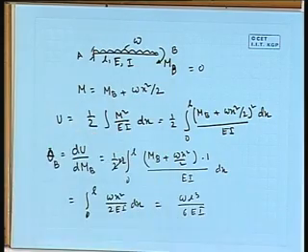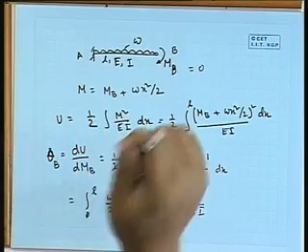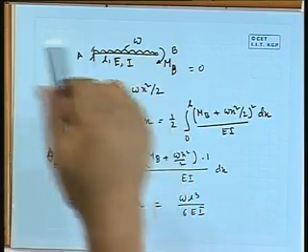So, in this problem we are interested not in deflection, it is slope, and there should be a moment. First of all, we should know there should be a moment there. So, force is corresponding to displacement, and moment is corresponding to slope. So, there should be some corresponding moment, and there is no moment.